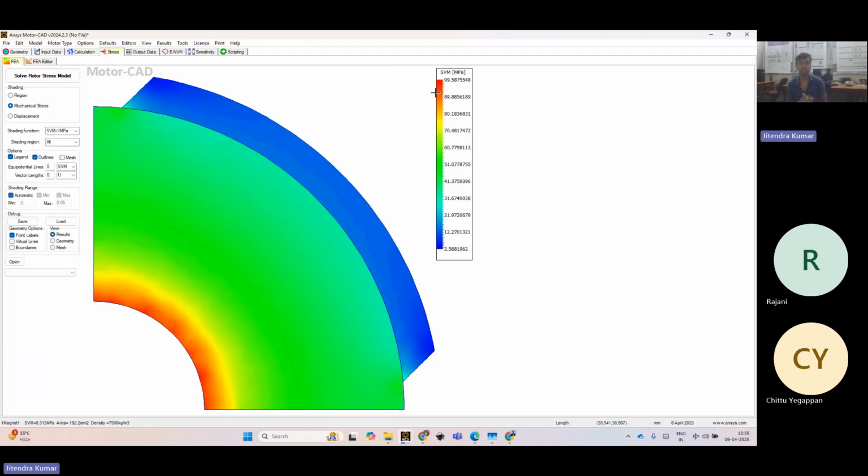So that's why in synchronous reluctance motor, if we have gone through those lectures, we could not place as many barriers as we want. Like we could not place 10 flux barriers in a small pole. What will happen? It will reduce your mechanical strength because there are so many bridges, right? If I have an example of synchronous reluctance motor, I could also show it at the end of the session if we get some time. Okay, so this was the one thing.